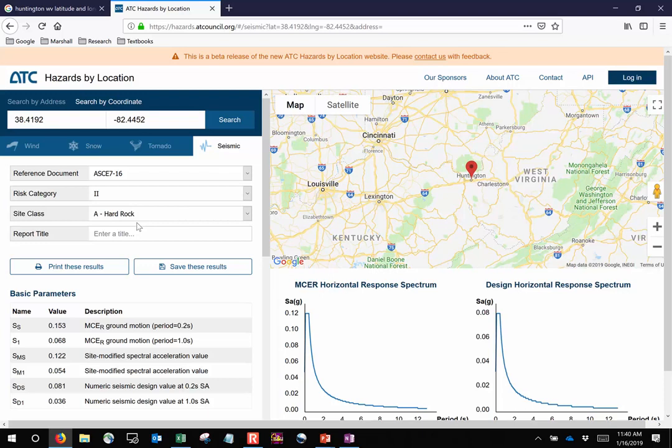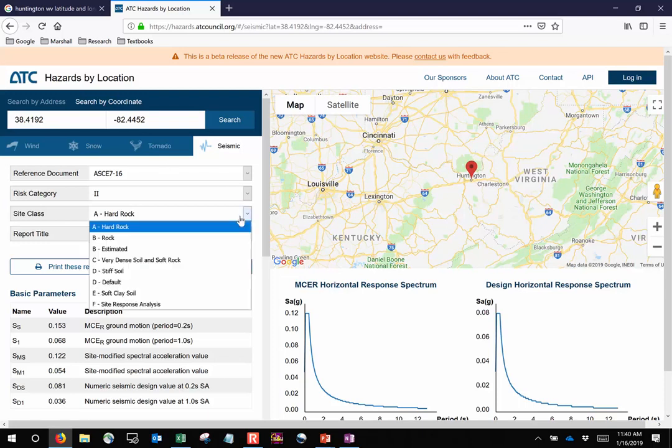to, let's say, a given structure is going to be dependent upon the type of soil that is at that given site. In other words, I don't think that clay would transmit the accelerations in the same manner as a dense rock would. So the soil characteristics do matter, but pretty much from a 30,000 foot view as far as we're concerned. And so if you go into the site class, there's a series of them. Stiff soil is essentially the default.